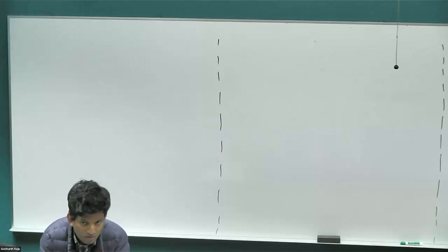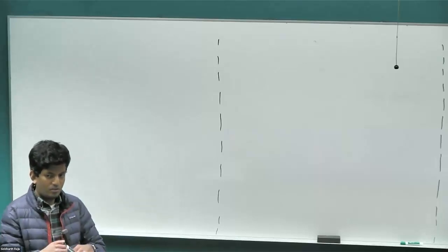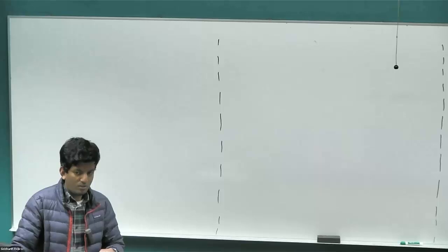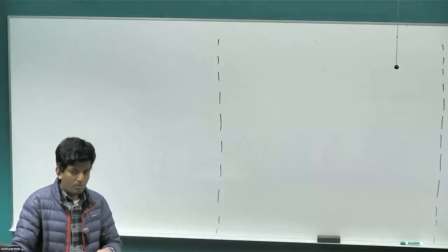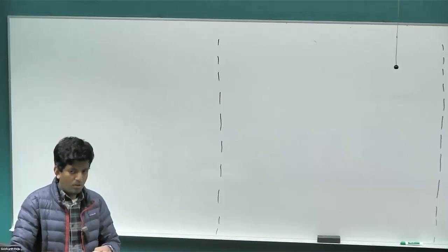John? Yeah, so you get that they should all have the same magnitude, right? Which you get by dividing the magnitude of the space vector by 1.5. And then I did it by using the cosine of the angle. Okay. And then they're all phase shifted. But I think the formula that we have, you put e to the j0 and then e to the j 2 pi over 3.